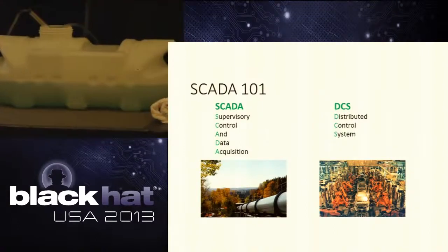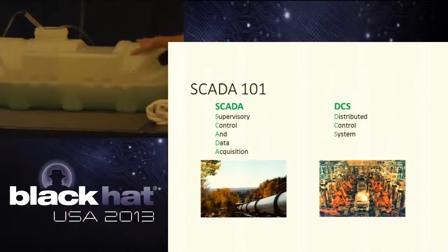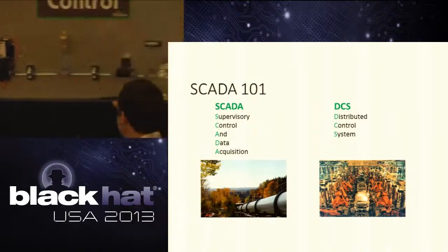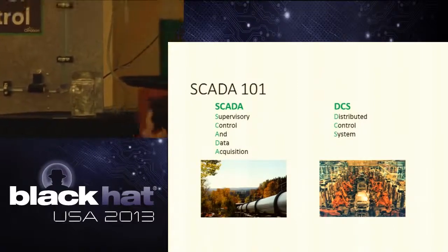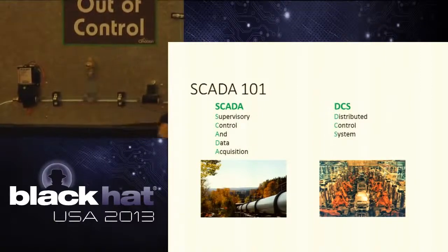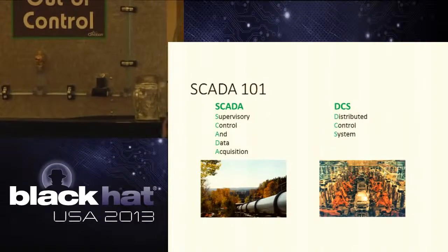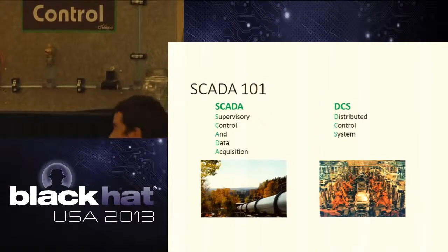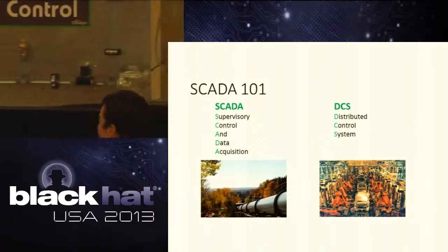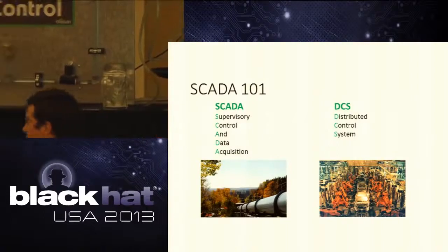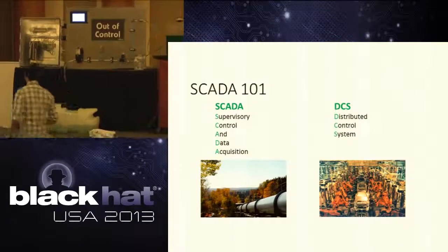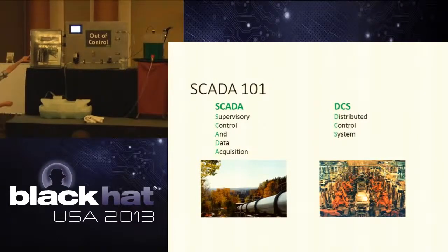Just to give you a brief overview of what we have, we have a simulated well itself. It goes up to a pump, then over into an isolation valve, and then up into our simulated tank. One thing that we also have here is this little brass guy, a pressure safety valve. You see those a lot in industry to prevent overpressures, but sometimes in production you'll have this pump, an isolation valve with no PSV in between. But we had to put one in just because we don't want to spray water everywhere. One other thing that we have up top is this little screen right here.